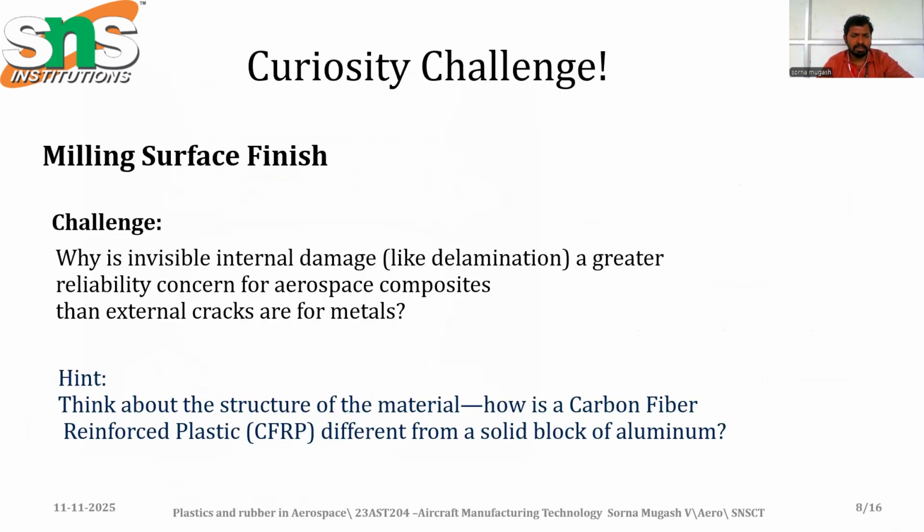The curiosity challenge: this slide raises a question. Why is invisible internal damage in composites more dangerous than external cracks in metals? The reason is that metal shows visible cracks on the surface, but composites are layered materials where cracks may develop inside without any surface indication, which makes detection harder and requires advanced inspection methods.